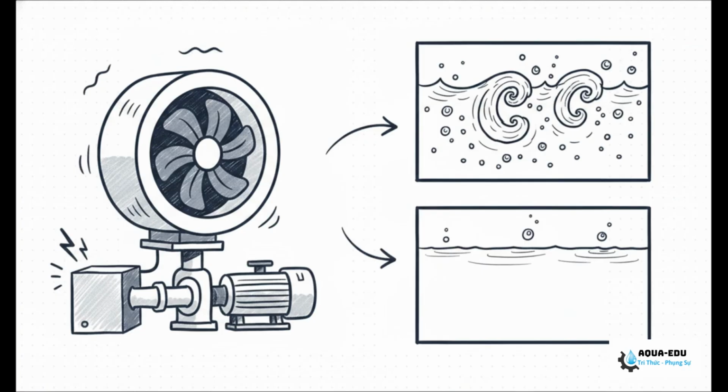So, how does this actually unfold on the floor? Picture that jarring silence. If you're on shift, the very first symptom is just the sudden, eerie absence of noise. The blowers and pumps go completely quiet, maybe except for the warning beep of a temporary UPS. Within 10 to 20 minutes, that rolling, turbulent agitation on the surface of your aeration tanks completely vanishes as the last trapped bubbles pop. The surface just gets unnervingly calm and still.